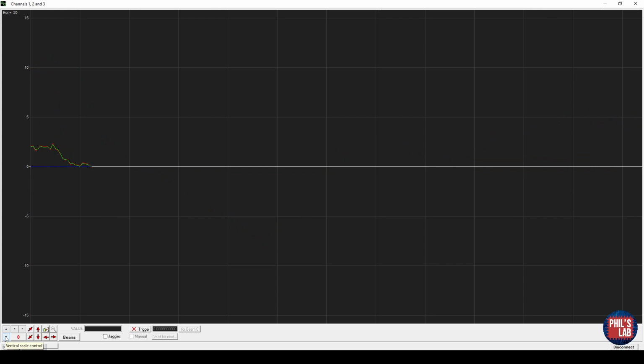I can zoom out, I'll start moving my pressure sensor, or rather the board, up, and you can see because I've inverted the pressures, I'm climbing up, which is what we expect, and I move the board down. Now I'm putting it on the table again, which should be around 0, and you can see it doesn't quite reach 0. So it keeps drifting, moving around, but we're staying within a certain band. So I can move it below the table. After initial jump, it actually goes below 0. So our initial function or pressure sensing seems to work in some way.